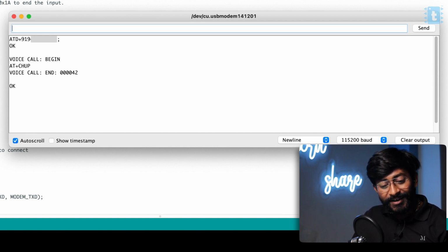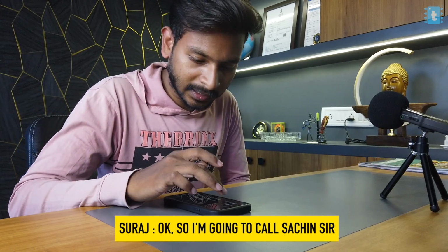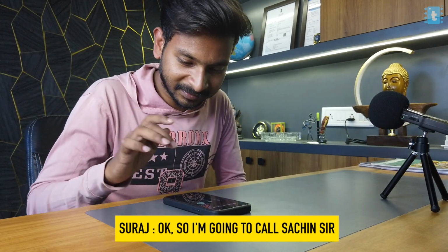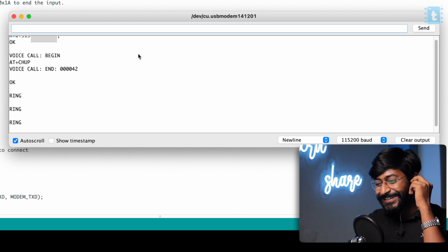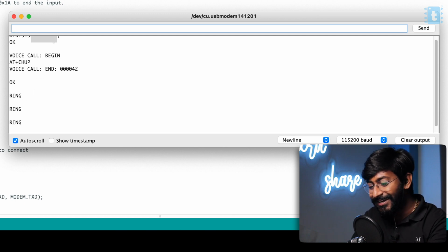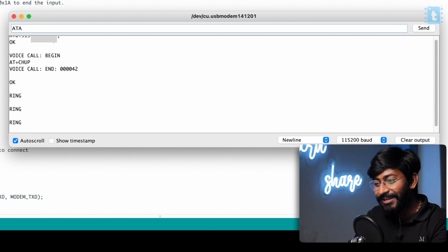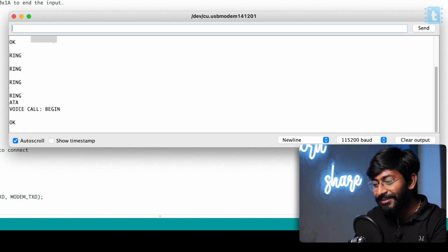Okay, I'm going to call Sachin sir. Okay, so it is saying ring. That means we are getting a call. So we need to type the command called ATA to receive it. And yes, voice call begin.